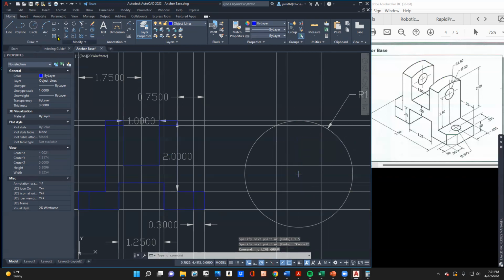Let's do that again. So you got to be really careful. Let's put a construction line on there. So essentially what it's saying is if I do the offset from this, it's 1.5. So let's type in 1.5. You just got to be careful that you're grabbing the right line from the very bottom here. It's going to be 1.5. Enter. Oh, sorry. Okay. And then the center line here, all these lines, it's 0.625 to the center, 0.625.